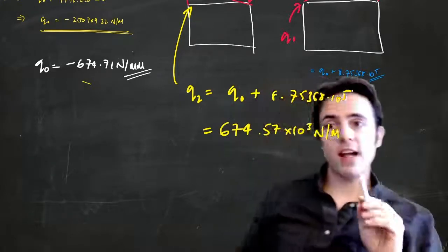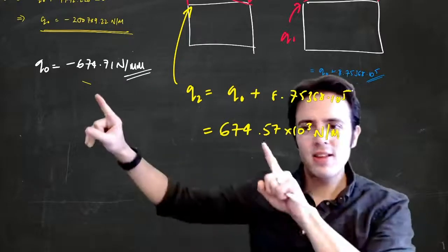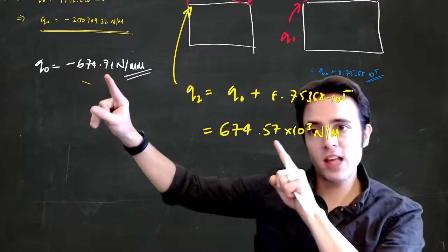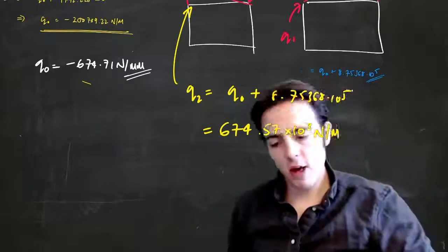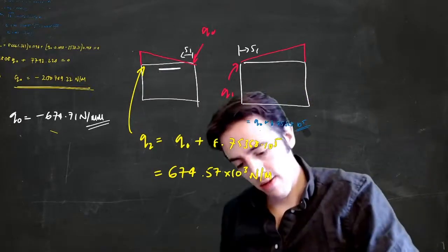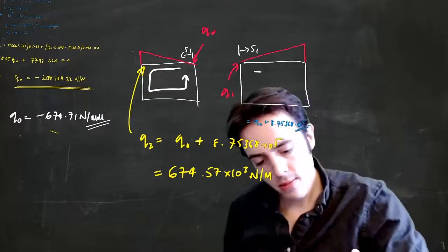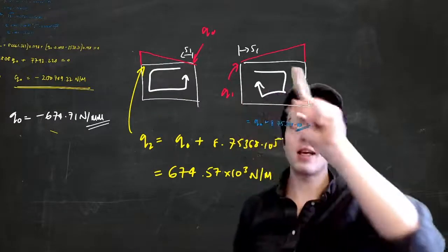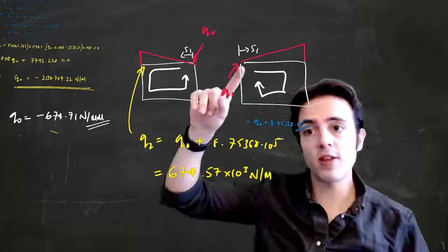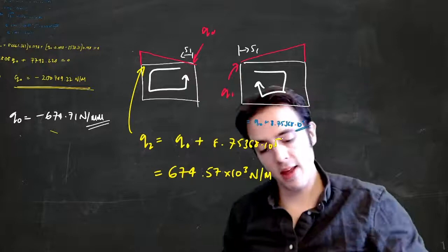Okay, so we're a factor of 1,000 out because I've done newtons per meter. This is newtons per millimeter. A small numerical error, probably somewhere in here, has led to an issue in the decimal places, and the answer is the opposite way round because the answer is the opposite sign, because I've defined my total S as being clockwise for this one, whereas it would have been in the other direction for this one. So the value of the principal value at each corner would have an opposite sign.